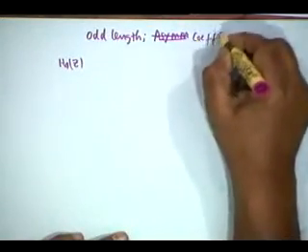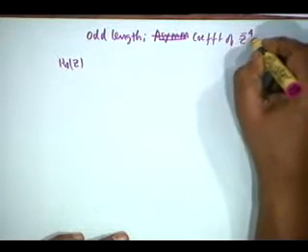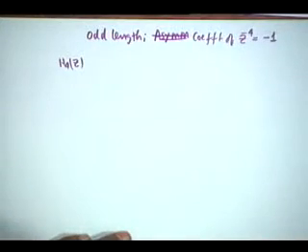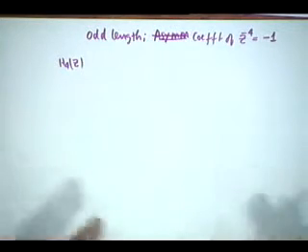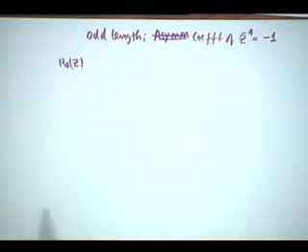Coefficient of the highest power term, coefficient of Z to the minus 4 is equal to minus 1 instead of plus 1. Then we shall have to bring in asymmetry, okay, to decompose into linear phase plus some other transfer function. We shall have to bring asymmetry.